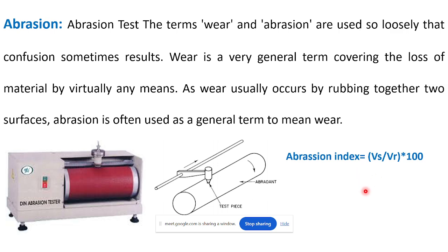If the hardness is low, for example, in case of conveyor belt, those materials used with the fabric usually have hardness around 50 to 60, but the top layer material or bottom layer material usually needs hardness around 65 to 70, and obviously it should have better abrasion resistance.